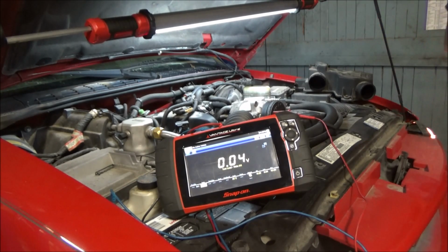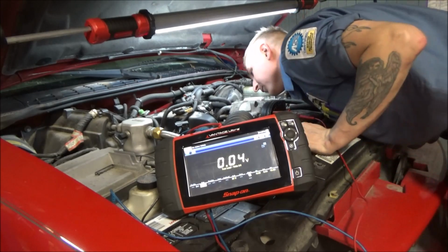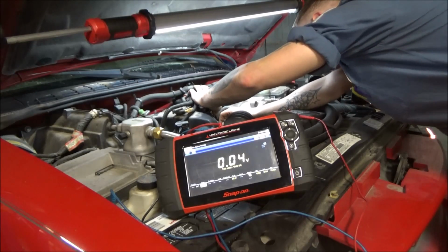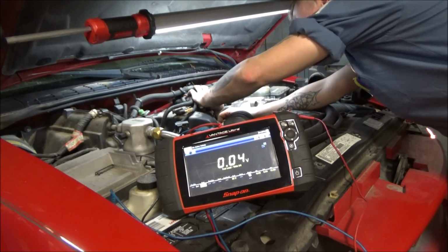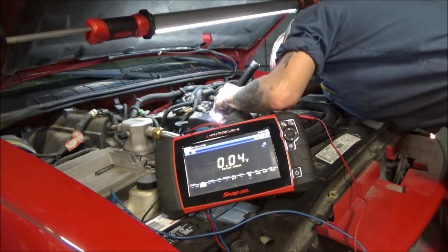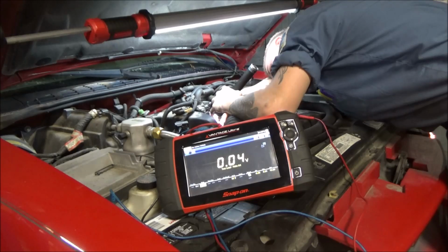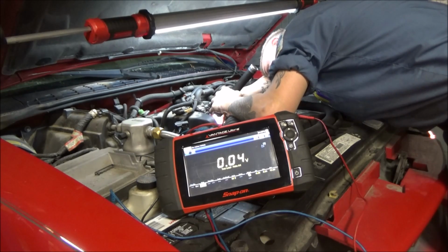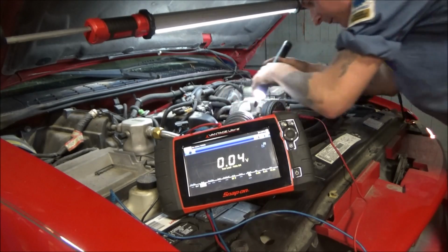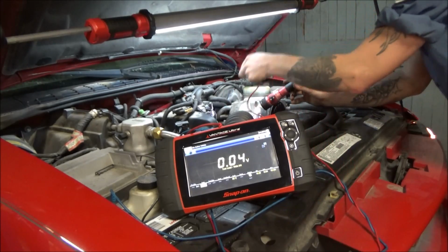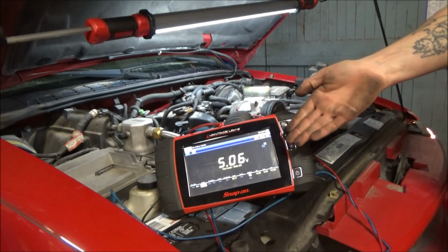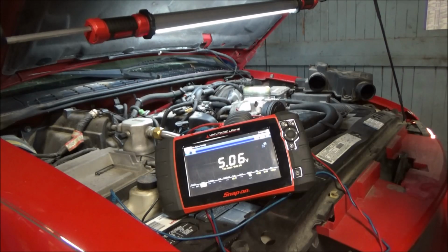So just turning the key on here, guys. I'm just taking a look at this sensor here. And I think the obvious first choice is I want to confirm that we have a good reference feed to this sensor. So I'm just taking a look at this connector, and I'm back probing this gray wire here, guys, trying to go in nice and straight. I feel like I'm in there pretty good, guys. I'm just going to hook my meter up. And as we can see on the Vantage here, we have a number of 5.06 volts.